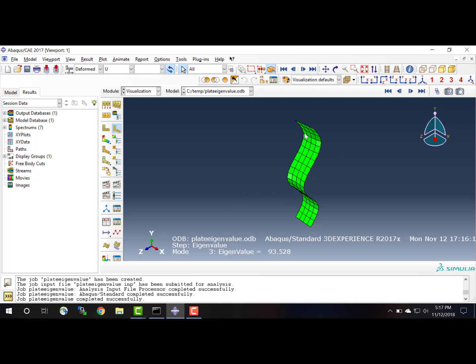Okay, so that's one way to get buckling modes and buckling loads pretty quickly for an elastic buckling problem. We can get the same thing from an incremental iterative analysis, and so in the next step, I will go through and do the incremental iterative analysis.